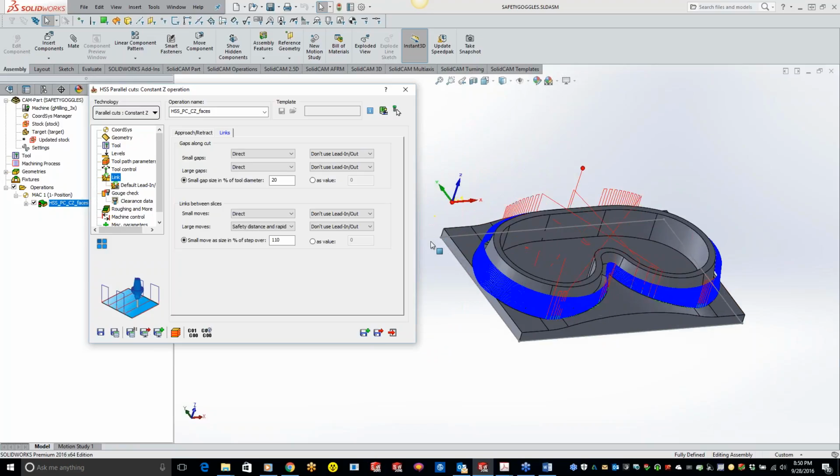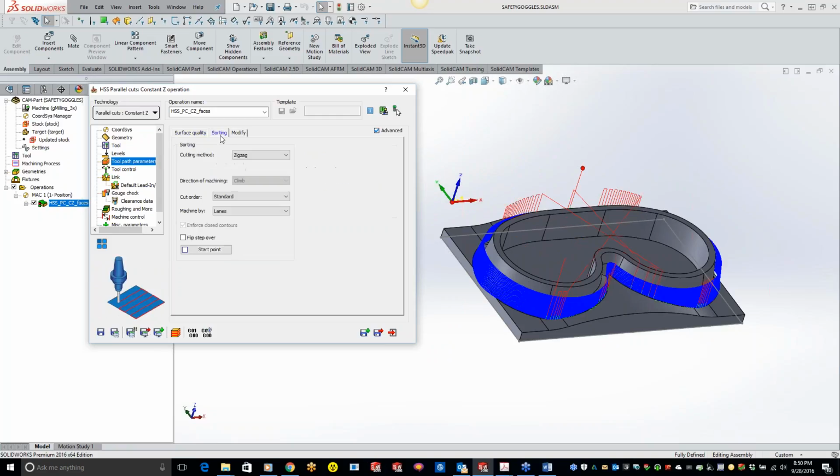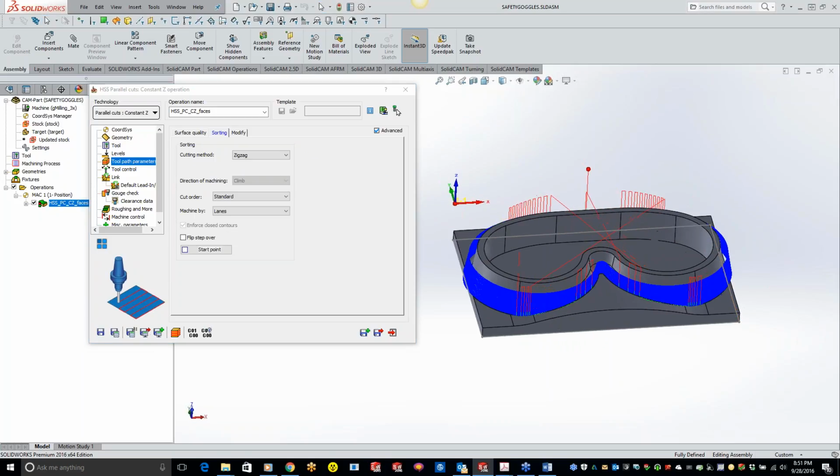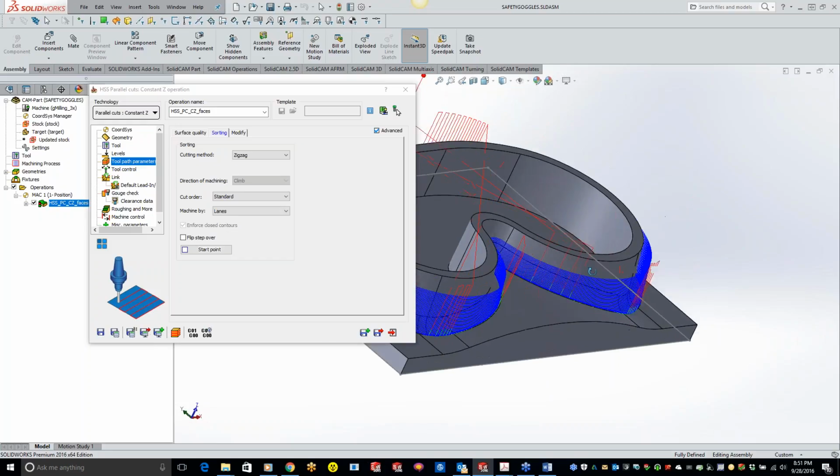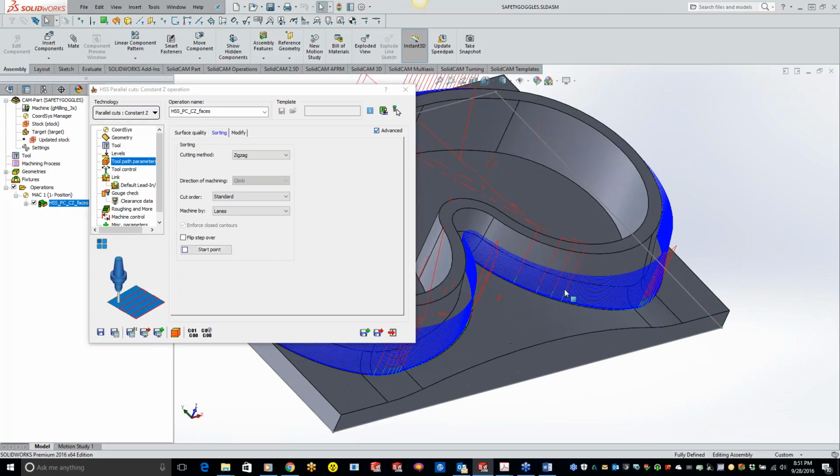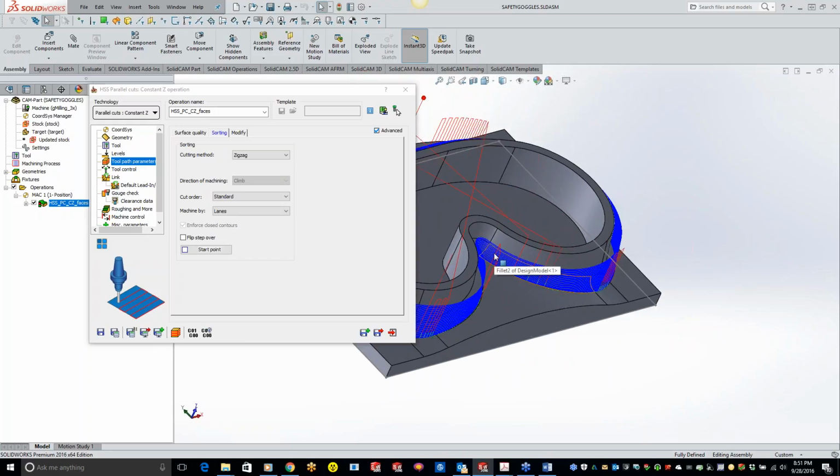And what I would actually do is set my toolpath parameters to doing a spiral. So basically just start at the top and do a nice corkscrew working its way down to get a real nice finish. But like I said, we don't have that option. So we're doing it as best as we can here, and we have a pretty full 3D part by just using the 2.5D standard here. So that gives a good representation of cleaning up that outside wall there.